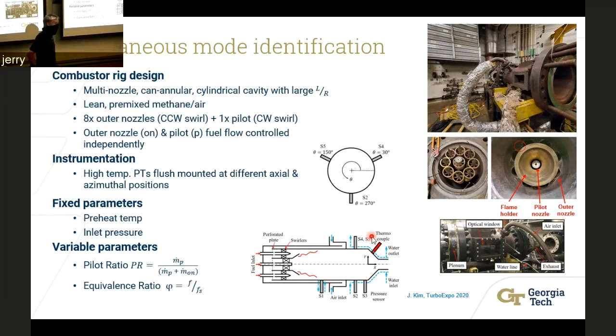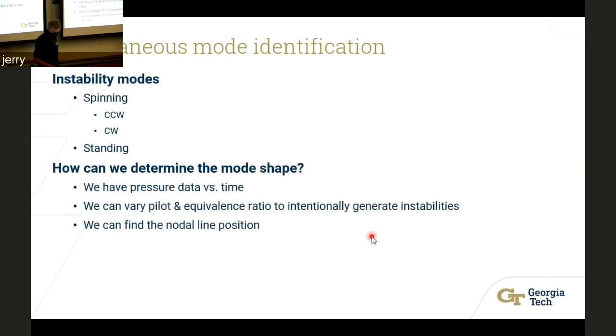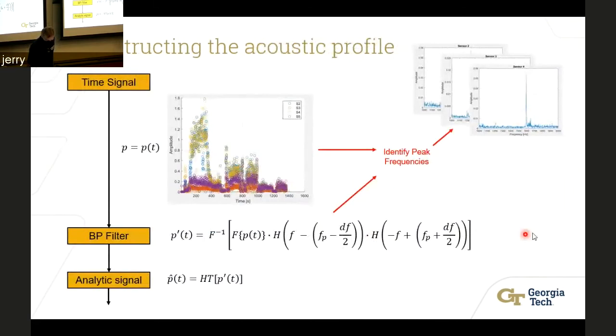And we were not able to adequately capture the effects of the instabilities, but we sample our data at 20 kilohertz. And that enables us to remove any effects of aliasing because our instability modes, if we go to this spot right here, and if I zoomed in a little bit, this is 1600 hertz. So we prevent the aliasing effect by sampling it at such high frequencies, around 20 kilohertz.